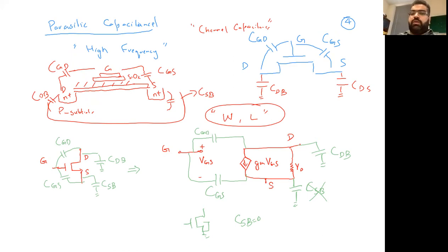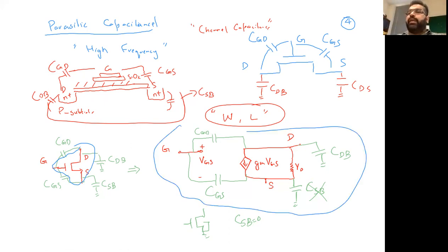doing only this configuration was relatively easy for us in terms of a hybrid pi model. But when I bring all these capacitance, the analysis will become difficult. We can do analysis using this hybrid pi model by bringing all the capacitance, but our hand calculation will be very clumsy. So the best way is to have the small signal MOS model without capacitance, find the midband gain, and bring those concepts of Bode plot, finding the pole at a specific node, and the Miller capacitance, and then find the overall transfer function. That's why we brought those notions earlier. Now we can apply them in plenty of applications or examples, and we can see this analysis. Yeah. So let's do this thing.